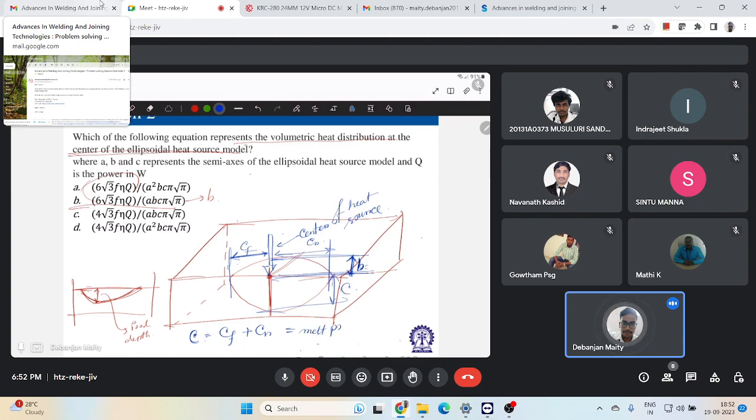So we do the experiment and then we measure from scanning electron microscope how much the melt pool length is coming, how much the width is coming, how much the pool depth is coming, and after that, you can put those values into your model and then simulate the complete process. Okay? So B is this Wi by 2, where Wi is my melt pool width,